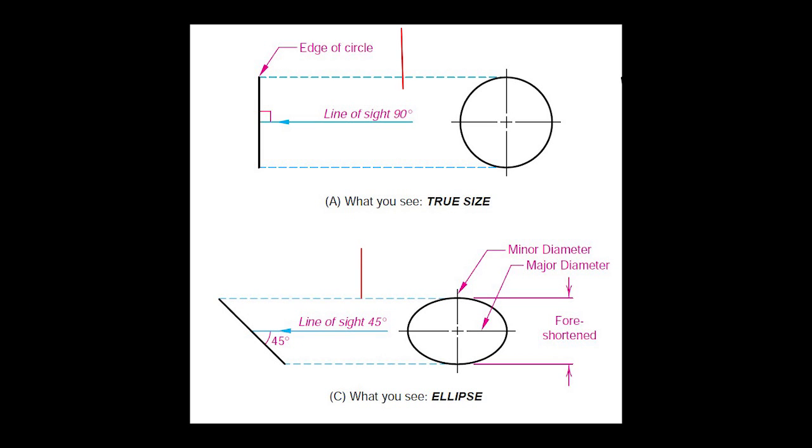You should be able to identify that the lines represent the front view of the object and the circle/ellipse represent the right side view of the object. Notice how in the top view the folding line is parallel to the edge of the circle. Hence we get a true shape or size of the face that is represented by that edge, and we see that it is a circle.